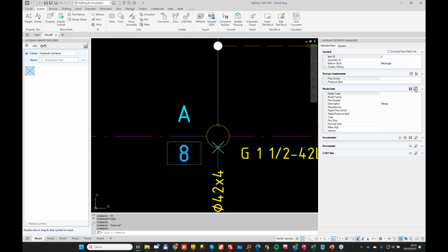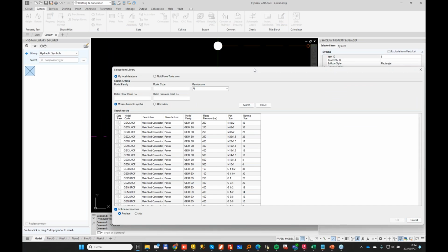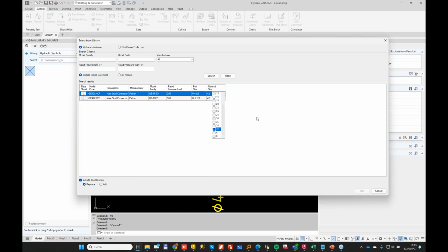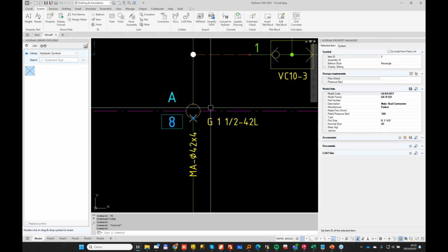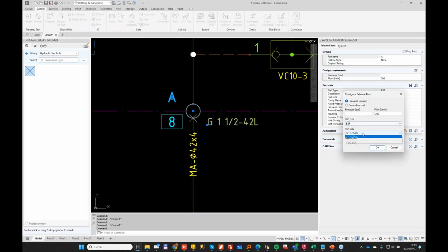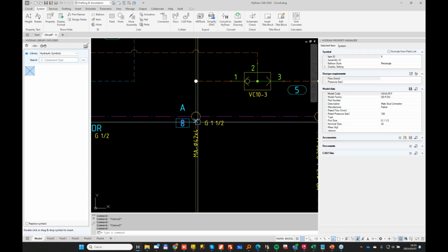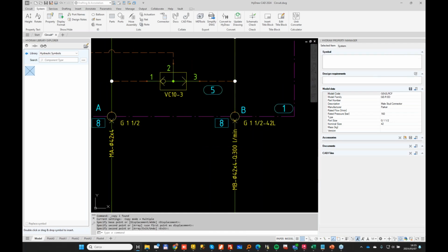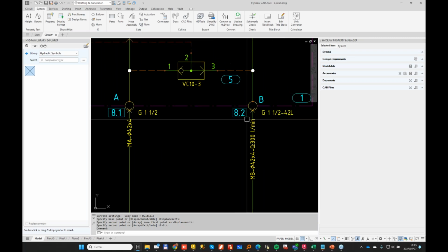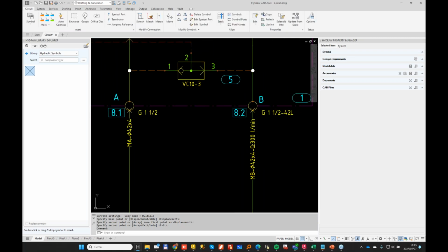So now let's get back here. When I take the fitting, I can search into the database. I need a nominal size of 42, and I need a G1 by 2. Okay. And so now in this case, really the port, I can use the standard ports, BSP, without describing the thread. So this is my fitting. I can copy my fitting here as well. And automatically they get doubled with the same item number with quantity 2. Also, I can copy the port size.